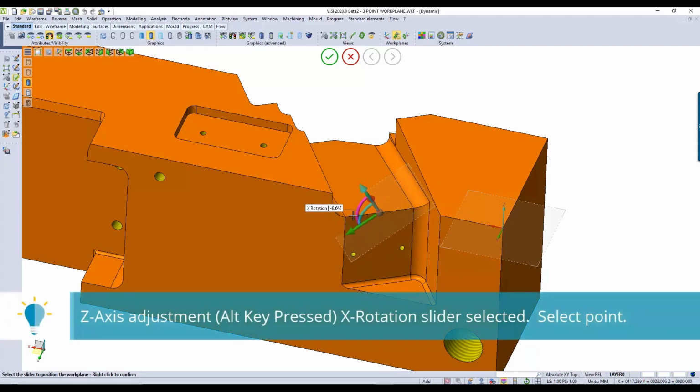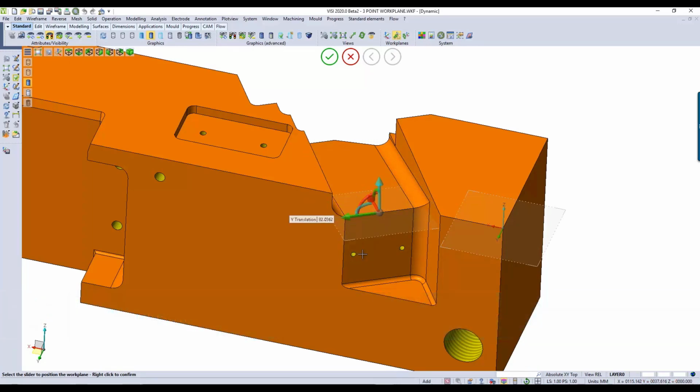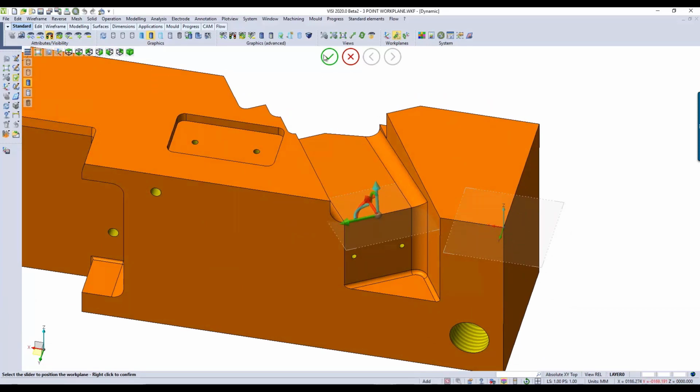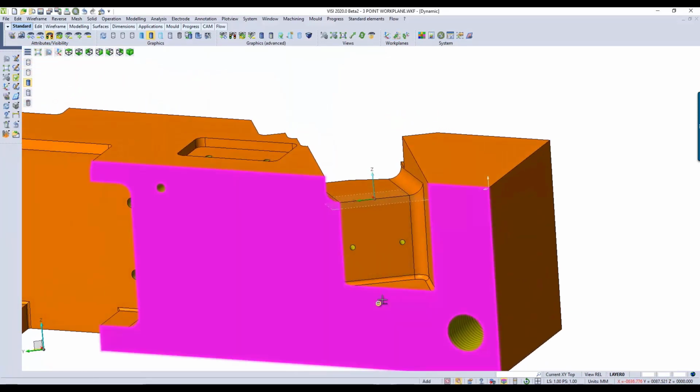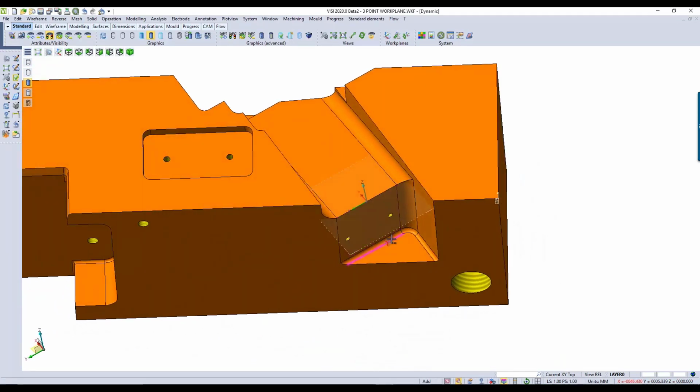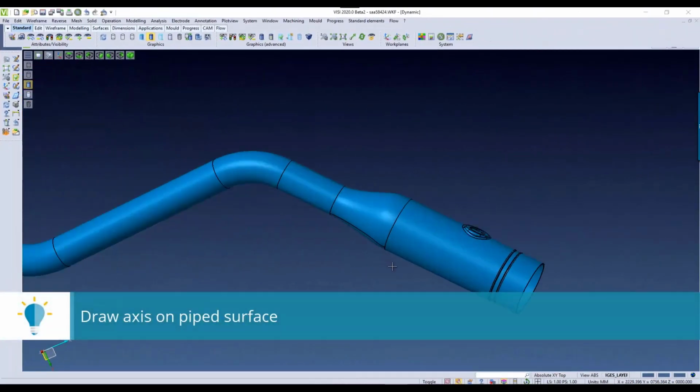And you can see, you could snap this to a different point. So as you can see, we snapped our X point and our Y point, thus making a work plane by 3 points. You can use the F2 button and it should automatically orientate to that specific view. So as you can see, that would be work plane by 3 points using the automatic work plane orientation.